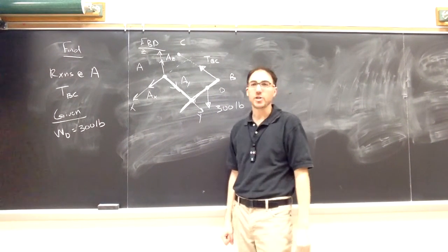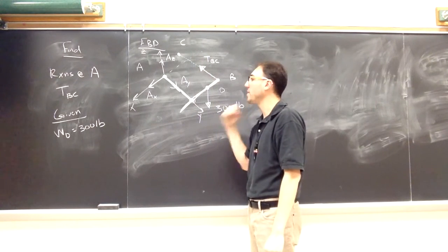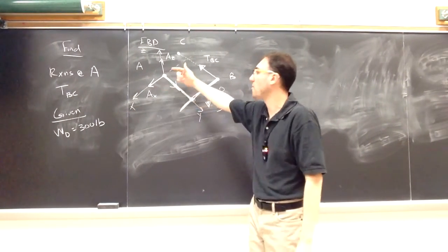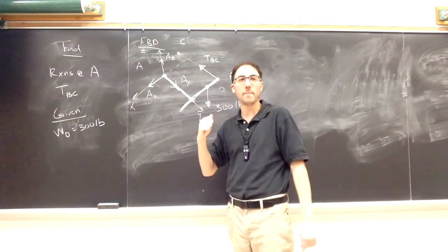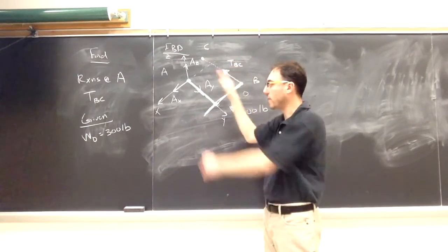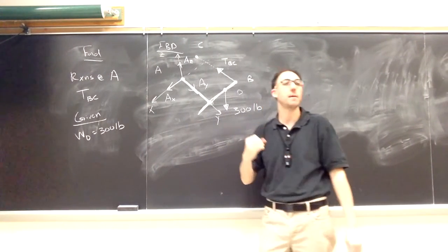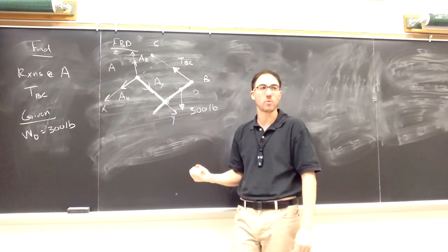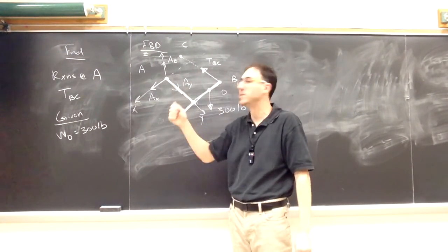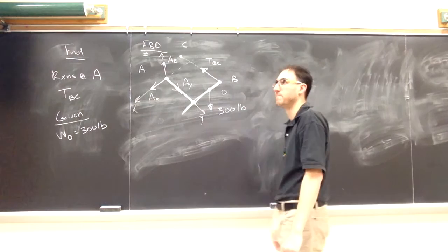Now we consider rotation. Again, we can consider one axis at a time here. Around the x-axis, is it prevented from rotating or allowed to rotate? It's allowed to rotate around the x-axis. When we're thinking about what is prevented or allowed, we don't think about the rope. We only think about does the pin allow it or prevent it. We don't think can the object actually do it or not. It's in static equilibrium, so it shouldn't be rotating. Yeah, it's not rotating, but the pin is not the thing preventing rotation around x. It can rotate around x, so I don't draw a couple.